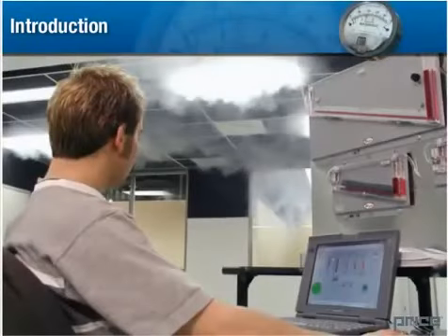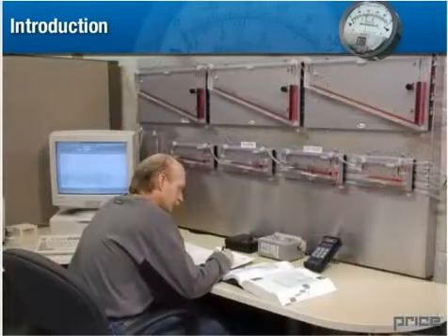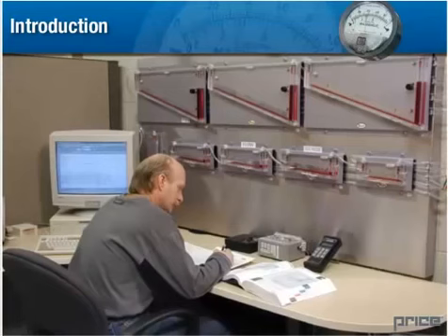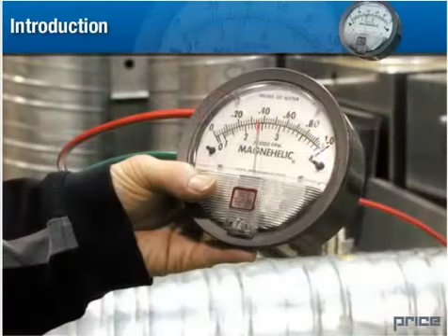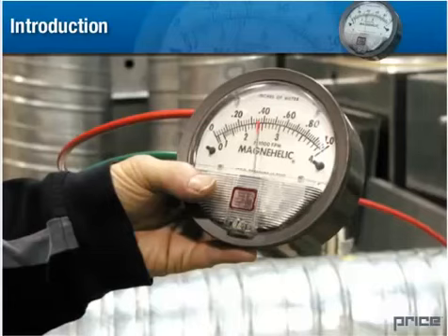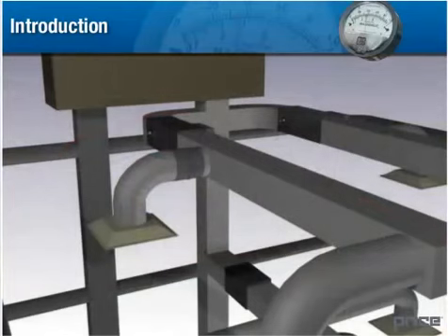When setting up and evaluating HVAC equipment, we must have ways of measuring air pressure in the system. Pressure measurements can be used to evaluate and improve the effectiveness of an HVAC system. With pressure measurements, we can detect undersized components that will cause restrictions in the airflow, overwork the air handler, and cause excessive noise. Pressure measurements can be used to ensure that airflow is balanced evenly throughout the duct branches and the appropriate amount of air is delivered to each zone.